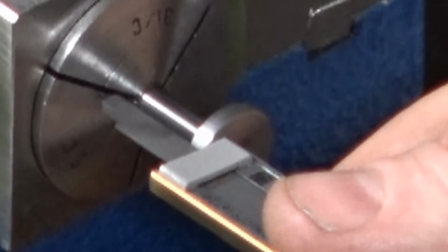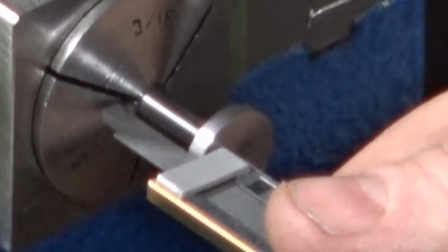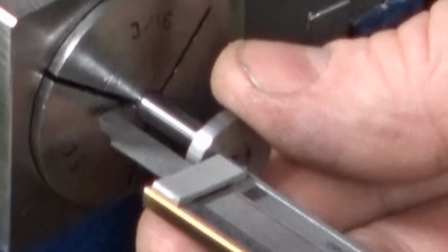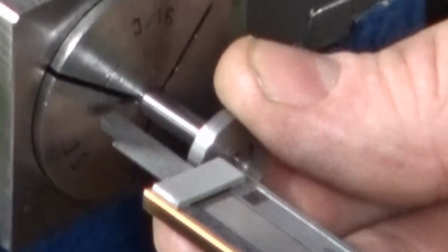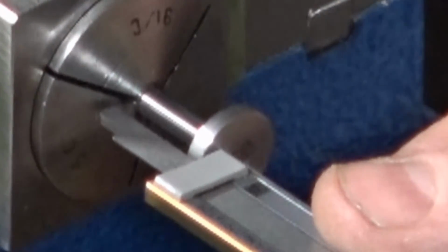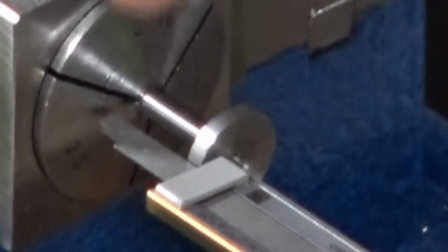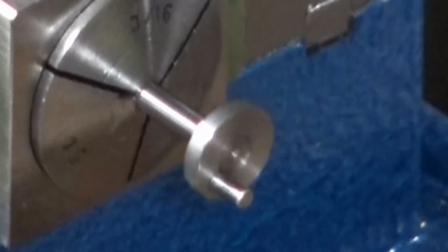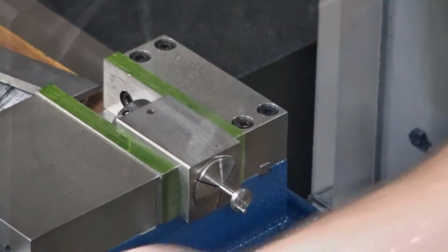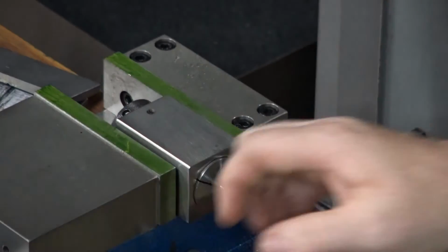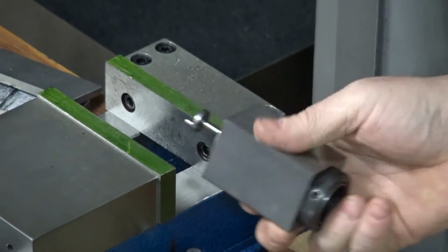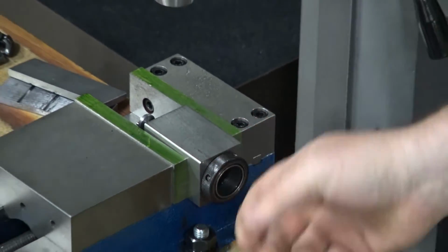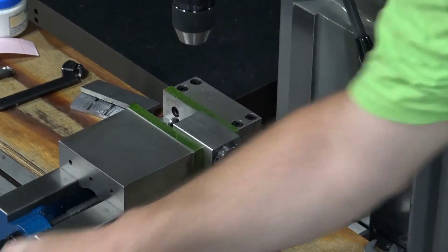I'm going to use the tail end, the stem of my calipers, and make sure that I have that much sticking out, okay? Now you kind of have to look at it and look at the relationship because the front of the collet's got a radius cut to it. But I'm pretty satisfied that I've got 750 thousandths sticking out. I'm going to turn my collet block around, okay? Lock my vise in.